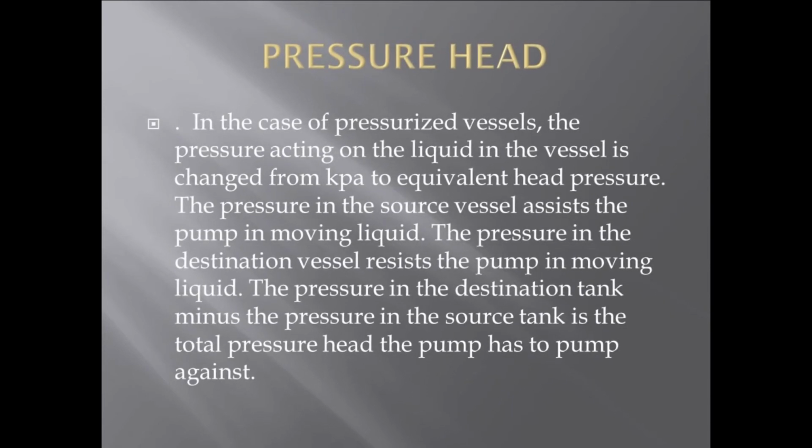In the case of pressurized vessels, the pressure acting on the liquid in the vessel is changed from kPa to equivalent head pressure. The pressure in the source vessel assists the pump in moving liquid. The pressure in the destination vessel resists the pump in moving liquid. The pressure in the destination vessel minus the pressure in the source vessel is the total pressure head the pump has to pump against.